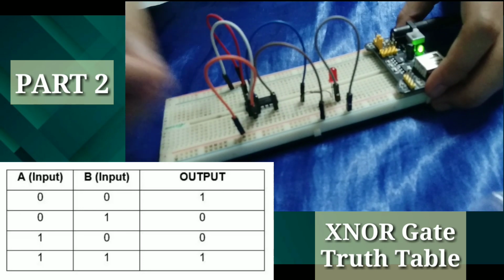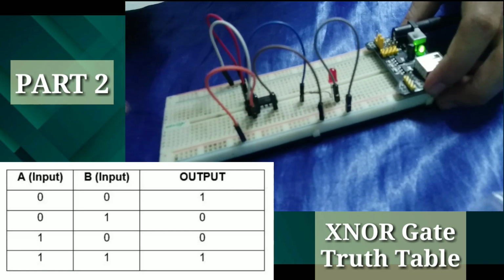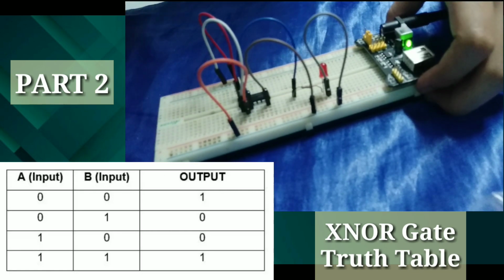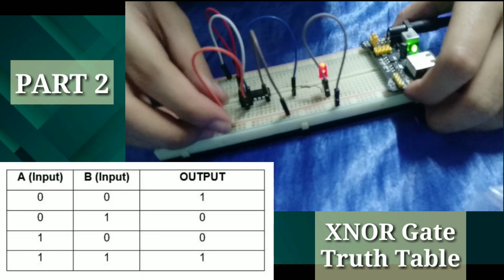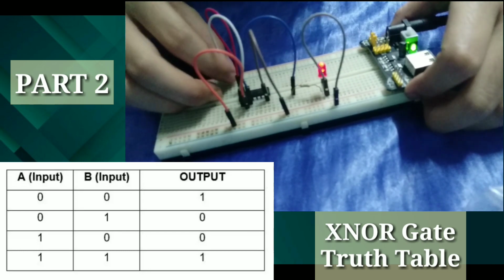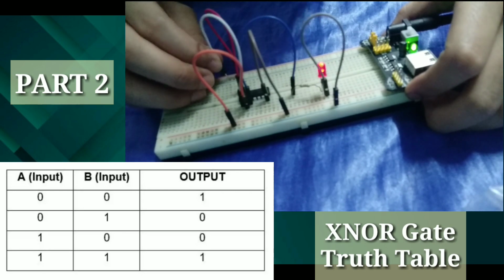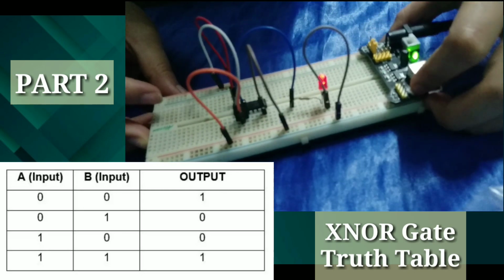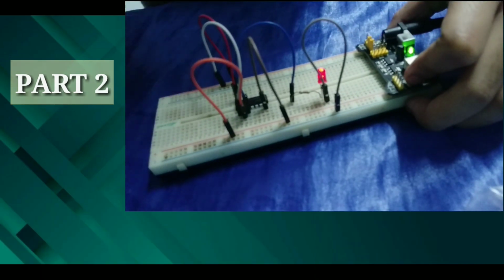Now, if A is 1 and B is 0, the output will be 0 as well. Now, for the last inputs, if both A and B are connected to our VCC, our output will be 1. So you can see the LED has been turned on. So that's our truth table for part 2.